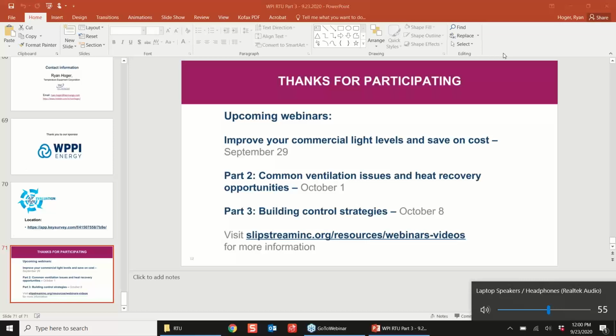And then you can move things around. Like these guys can slide back and forth to get the right tension on the belt, and they can slide in and out to get things lined up properly. We can also change out these pulleys or sheaves to get you a different amount of airflow. That's kind of the old school way of doing it, right? The newer way would be to have a VFD on here, and then we change the VFD to get different airflow instead of changing out the pulleys.